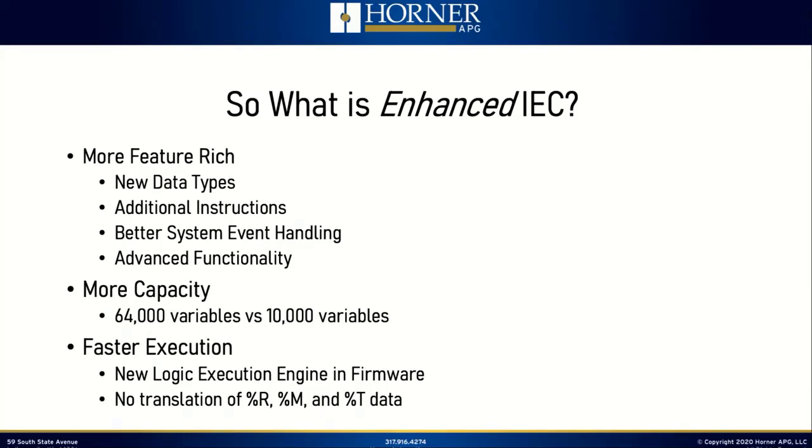However, general-purpose word variables and general-purpose bit variables, whether they're retentive or non-retentive, really have no relevance anymore with Enhanced IEC. Therefore, because there's no translation in between, the execution time is one of the things that has been positively impacted.